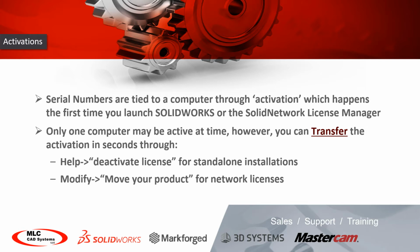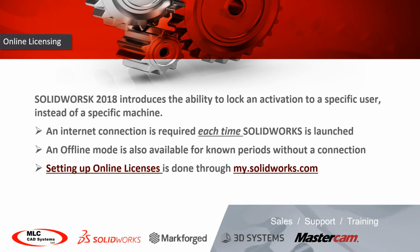Now, activation does use the internet at that point in time when it activates, and starting with SolidWorks 2018, we have introduced the ability to lock an activation to a specific user instead of a specific machine. This means that you could launch SolidWorks and be asked just to log into that computer to get the SolidWorks license, so I don't have to hit Help and deactivate. Downside there would be an internet connection is required every time SolidWorks is launched. If you like that flexibility though, there is an offline mode, so if you're traveling or you're going to have a period without an internet connection, you can run in that mode.